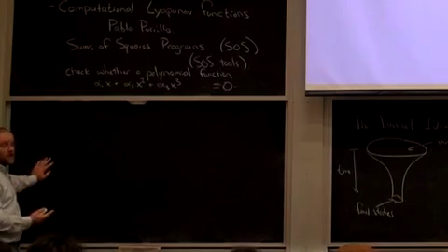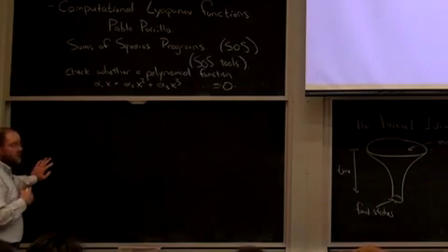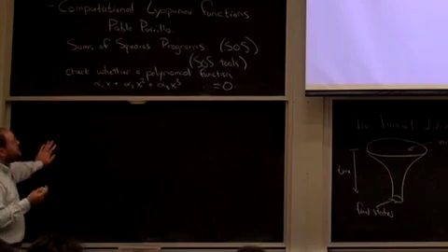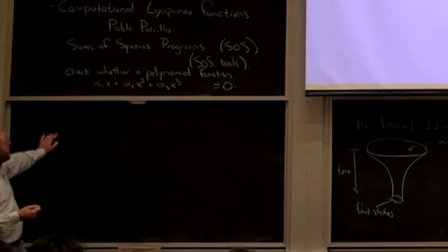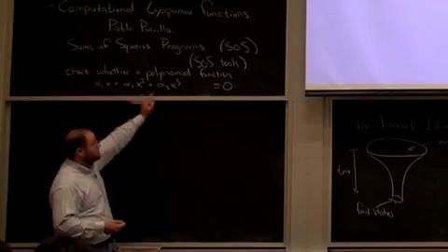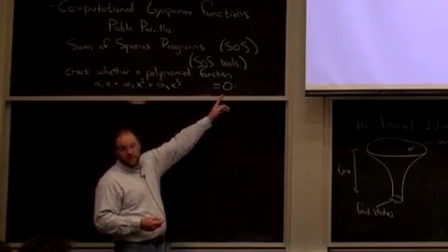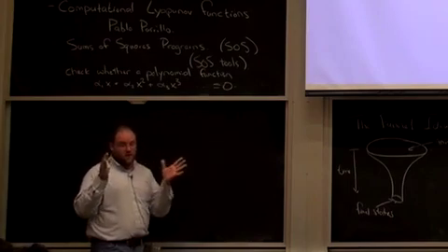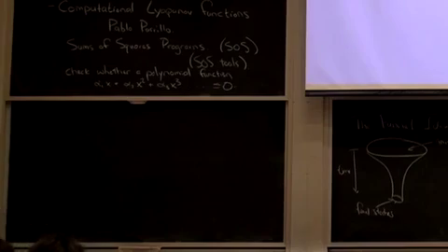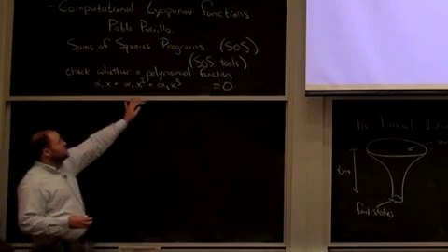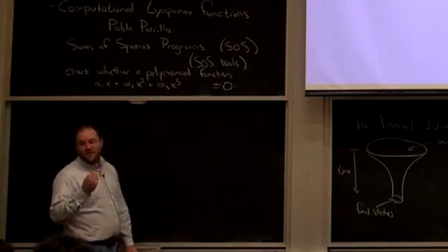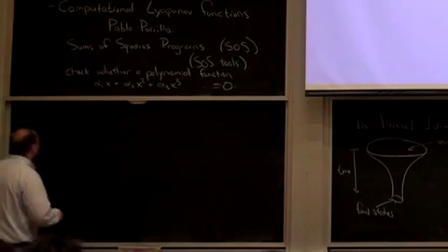What that allows us to do now, at least in the case of the LQR design, we've sort of worked it out. It's possible to now check whether a polynomial function is a Lyapunov function for the system. Right? Lyapunov functions have to have their derivatives going down over time. In order for a function to be a Lyapunov function, its value had better be going down at all times. Right? If your candidate Lyapunov function is even a vector polynomial function, then you can use this to check whether it's a valid Lyapunov function for your system. Okay?